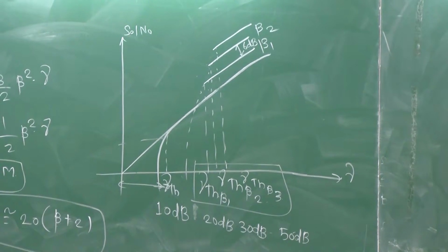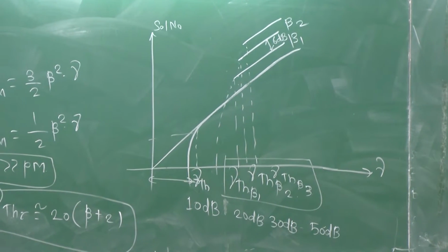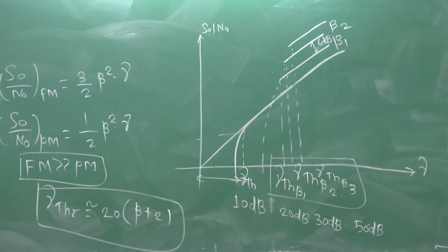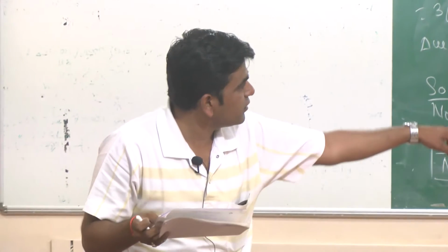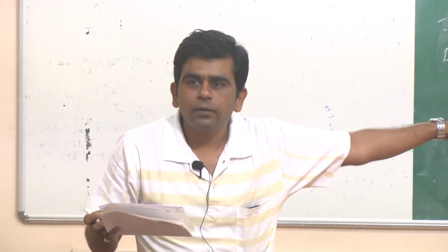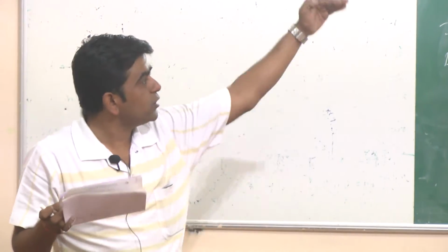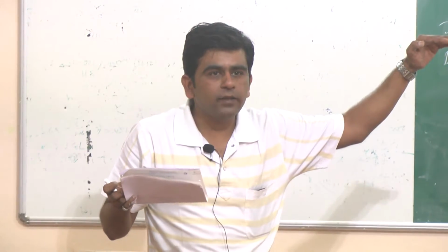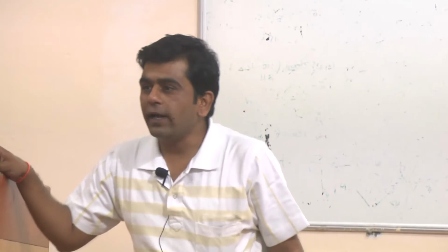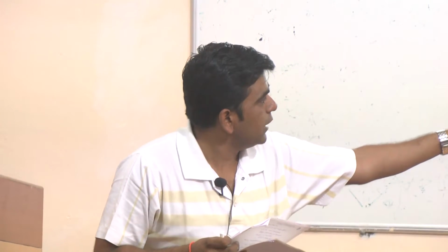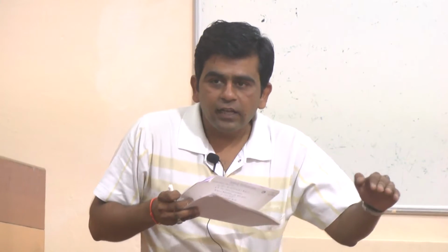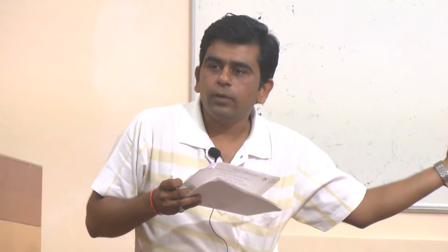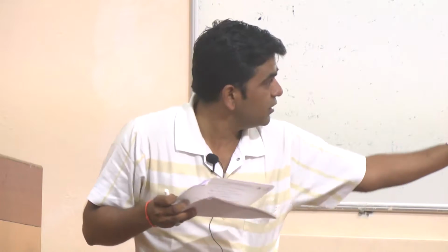For this 20 dB, yes, I can increase the bandwidth and move towards the angle modulated system, up to the bandwidth for gamma threshold beta 1. When I switch to beta 2, the higher bandwidth, what happens? The gamma threshold value for this second bandwidth is 30 dB, higher than my signal level of 25 dB.